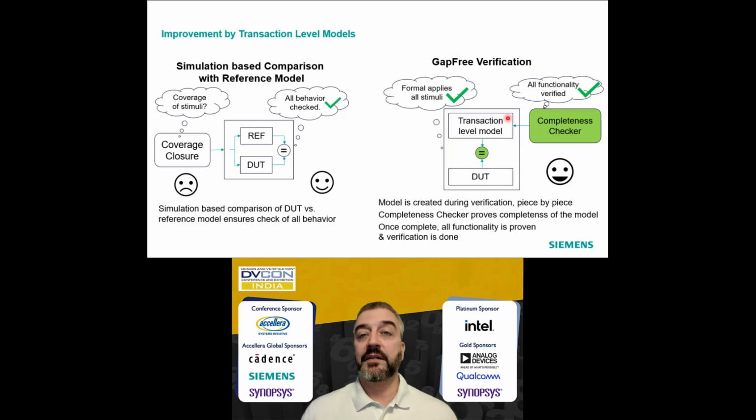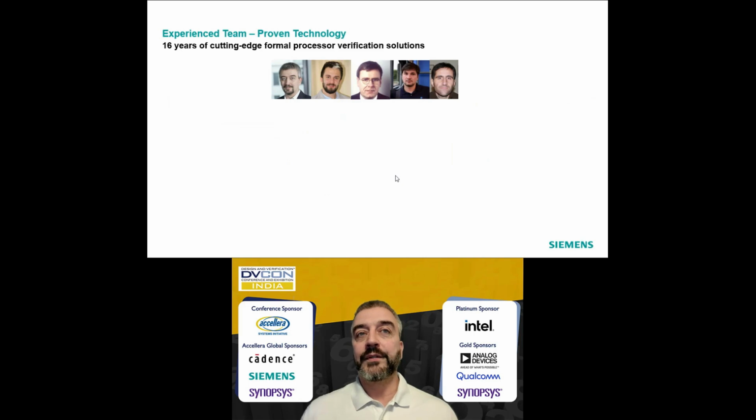So if you find some missing scenario here, it may point out that you've forgotten to verify a certain instruction or a certain register, stuff like this, kind of forcing you to really have everything in there. Now, these two things, the operational assertions idea for pipelines and the gap-free, of course, I can only hint at quite shortly in this tutorial/workshop.